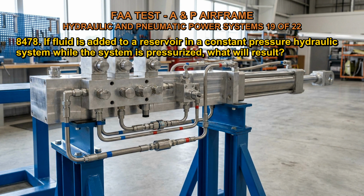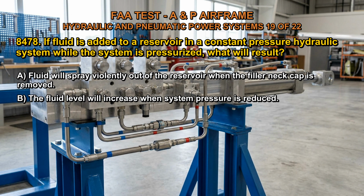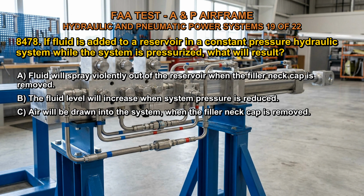8478. If fluid is added to a reservoir in a constant pressure hydraulic system while the system is pressurized, what will result? A. Fluid will spray violently out of the reservoir when the filler neck cap is removed. B. The fluid level will increase when system pressure is reduced. C. Air will be drawn into the system when the filler neck cap is removed. The correct answer is B.